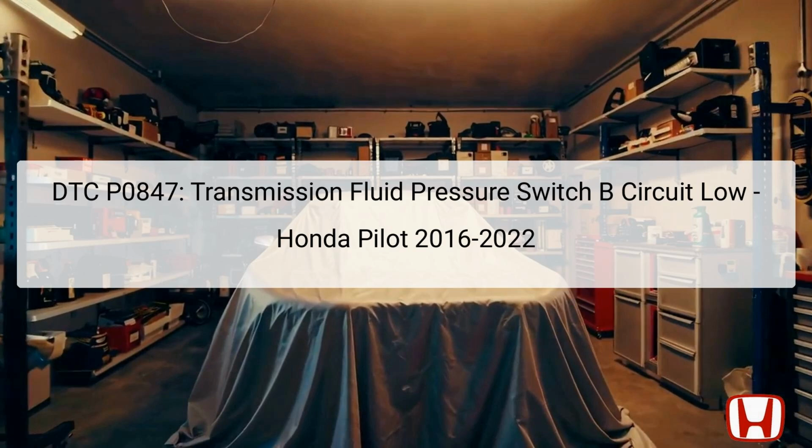Understanding the components involved can help in effective troubleshooting and resolution. The transmission fluid pressure switch B is primarily located on the transmission assembly and plays a pivotal role in monitoring fluid pressure, which is essential for proper gear shifting. Diagnostics, including the use of a Honda Diagnostic System, HDS, are necessary to assess the code's origin accurately. Proper troubleshooting will ensure the restoration of normal transmission functionality.